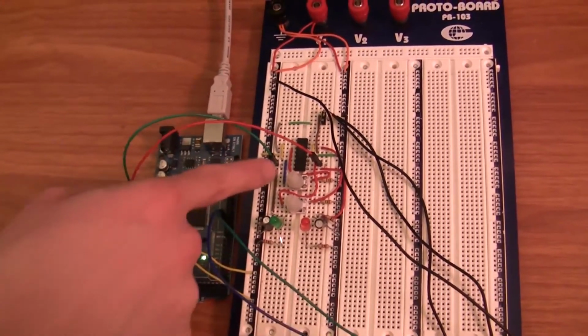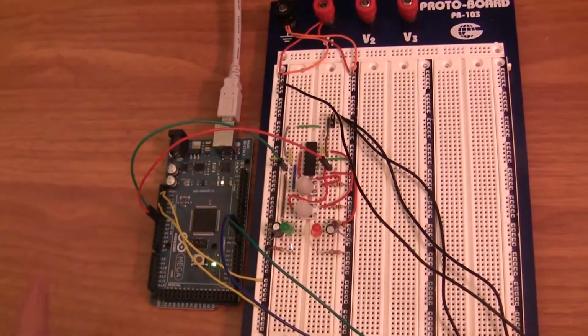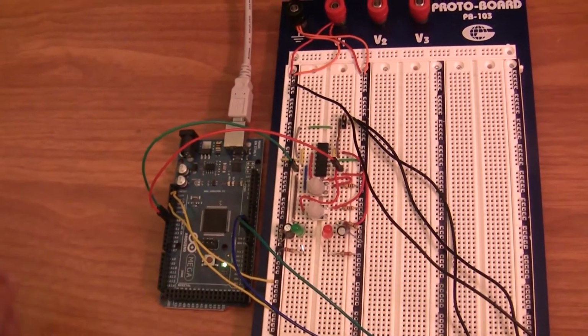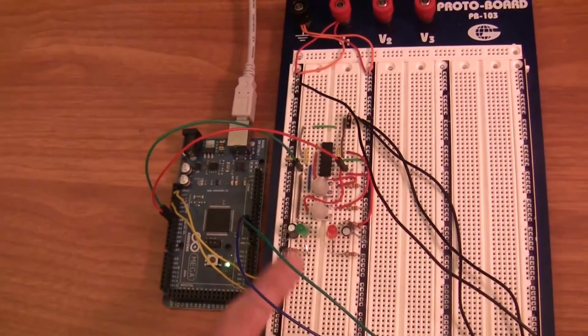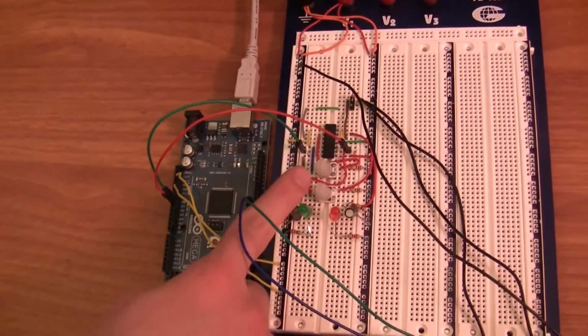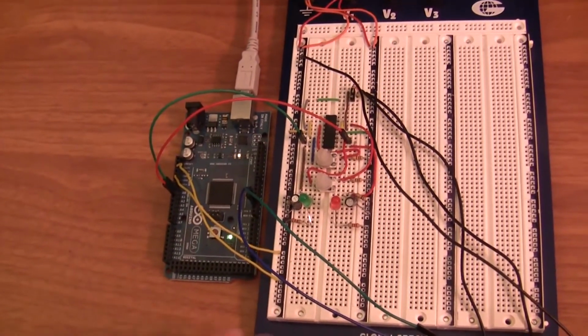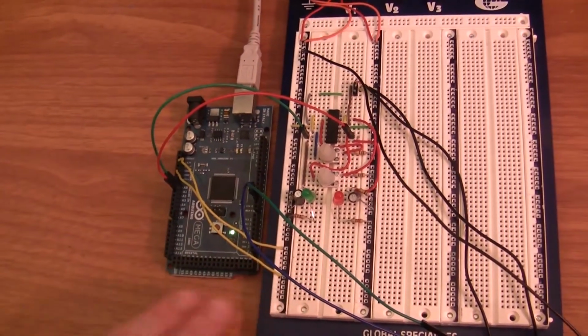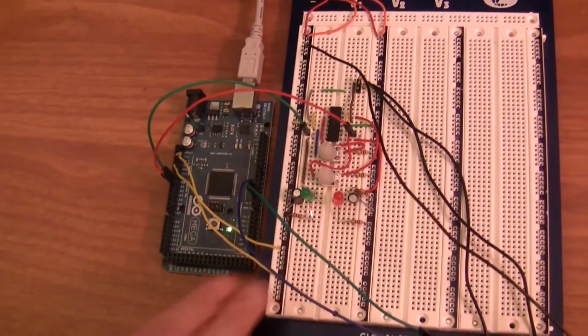Here we have the quad operational amplifier that we're using. So there's 4 op amps in here. The 2 on the left are the gain op amp and the buffer op amp for the left channel, and the 2 on the right are the gain and buffer op amp for the right channel. Down here we have our 2 potentiometers, which are used to adjust the gain on each signal so that we can get it just where we want it. And we have LEDs that indicate the approximate amplitude level of each stereo signal.